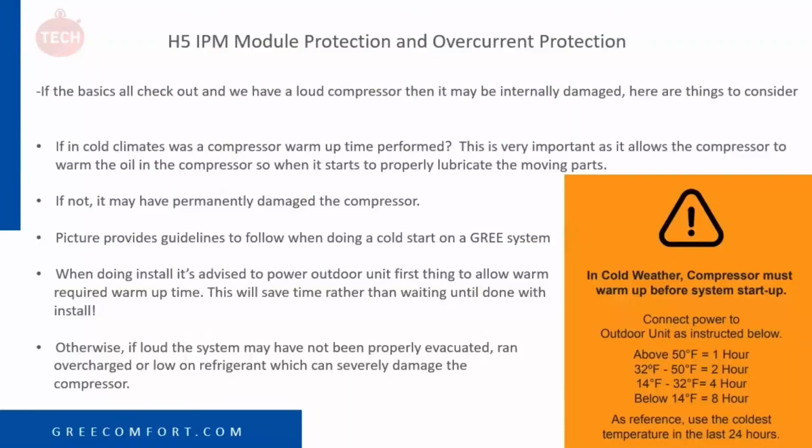Here are some things to consider. If you're in cold climates and the compressor warm-up was not performed, that would definitely lead to some damage to your compressor. This is very important as it allows the compressor to warm up the oil in the compressor, so when it starts, it properly lubricates the moving parts of the compressor. If it was not, again, it can permanently damage your compressor. The picture to the right shows proper warm-up time and gives you different parameters.